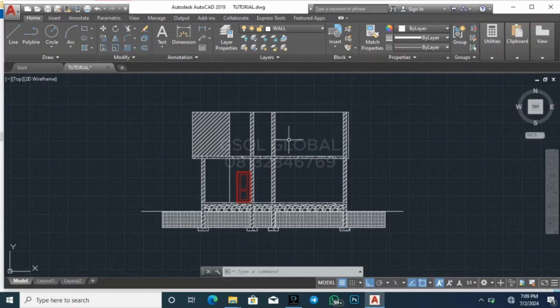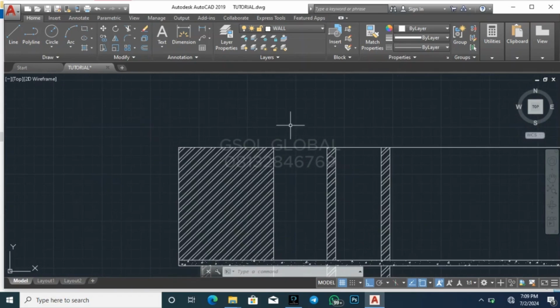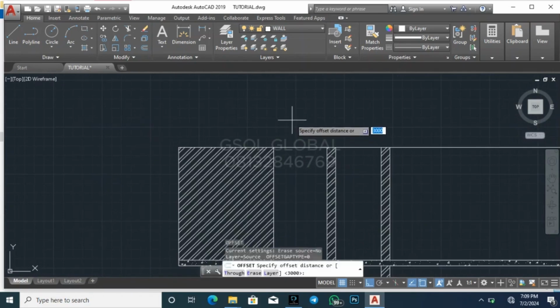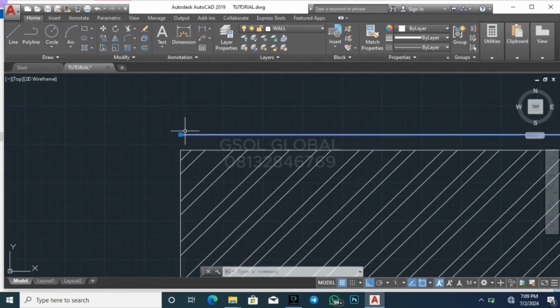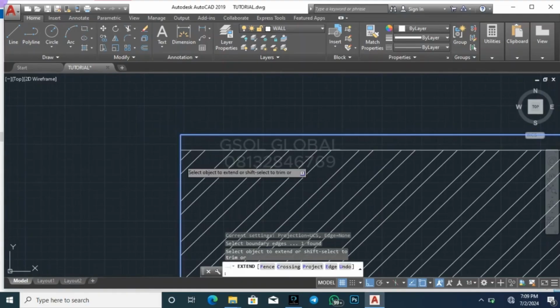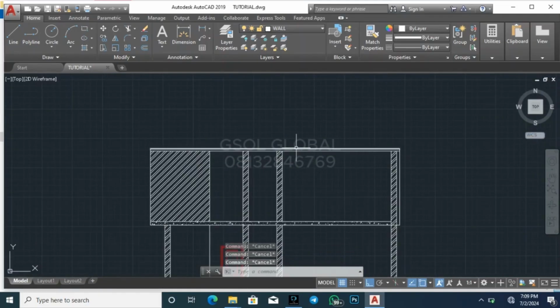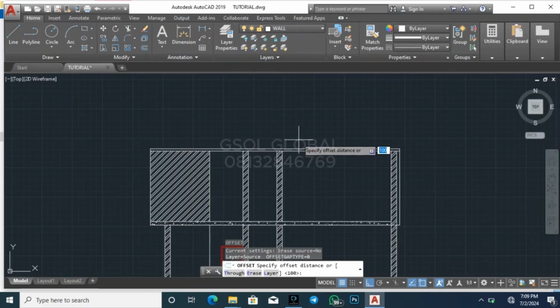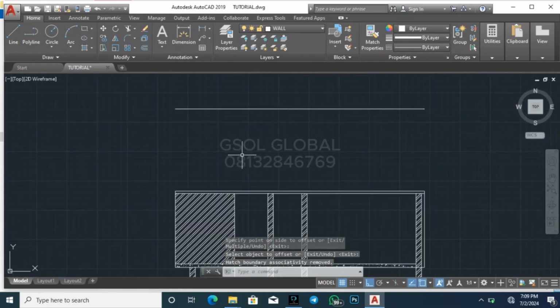All right. So for this now, we are going to be doing that of the roofing. So first of all, I will go to my tie beam. All right, as usual, the same way we did that of the bungalow. So I'll go to my tie beam. So I will extend all of this line and then extend this one. So I'll make an offset of 3.5 meters for the king post height, which is also the roof height. All right. So 3500 offset upward.